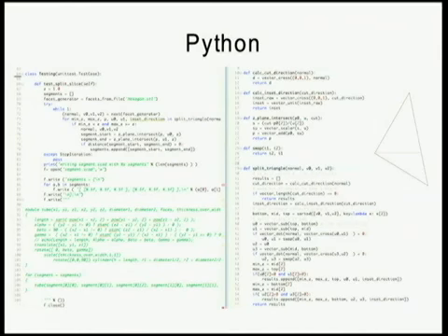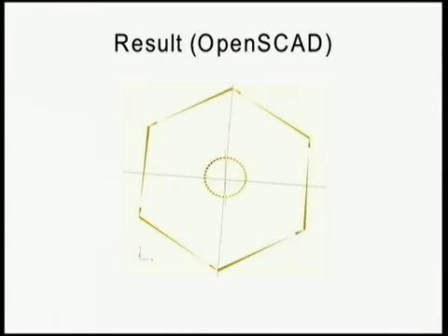Once you get the edges that cut your triangle, you just use the intersection equation we saw earlier, and then you can write that in a text file. I'm using OpenSCAD in this way, and the result is this. So now this is not much, but already from any 3D object, you can have the whole contour and inside, and if you just send that as G-code to an extruder, you're able to build 3D models. So it doesn't require that much mathematics yet.